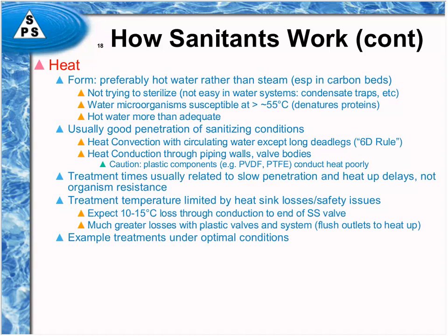Example treatments under optimal conditions, these are just made-up things, so don't go to the bank with these. But for instance, if you have a 60 to 65 degree water treatment, you're going to need to expose the system for at least 8 hours. And you've got to be careful, because with that 10 to 15 degree loss at the valves, you may not be achieving a sanitizing condition if it's a metal system.